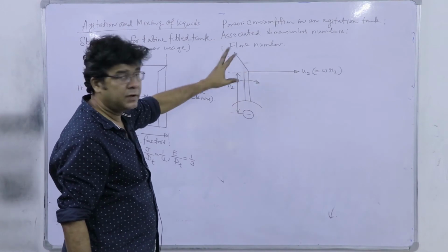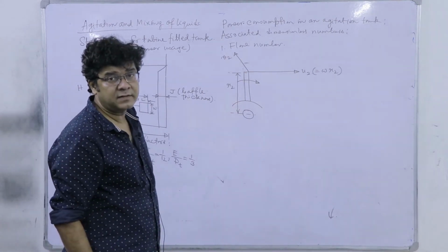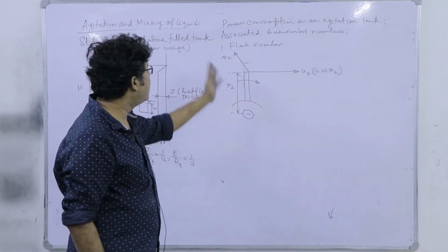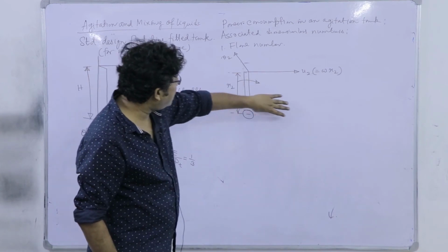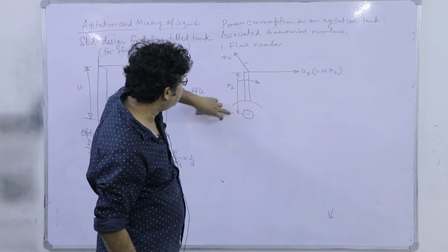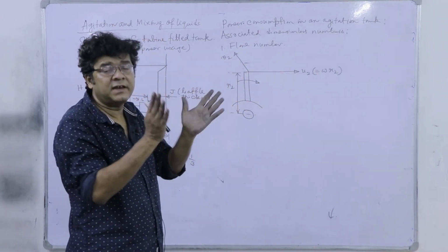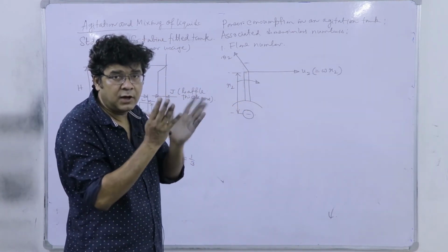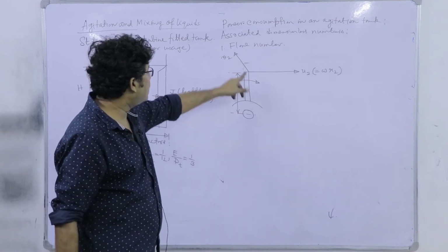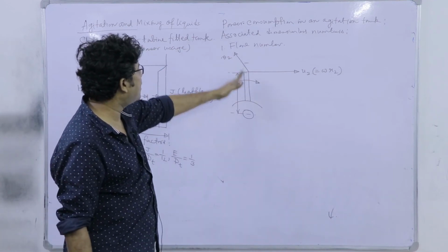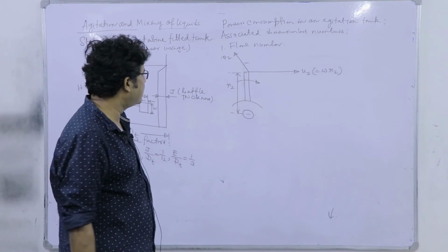It's true if we have this perfect guidance assumption we have discussed in fluid mechanics. However, as we have a finite number of these blades like 4 or 6 or 8, right, there are no infinite number of blades with very small and infinitesimal thickness. So, basically there will be divergence from this perfect guidance direction.